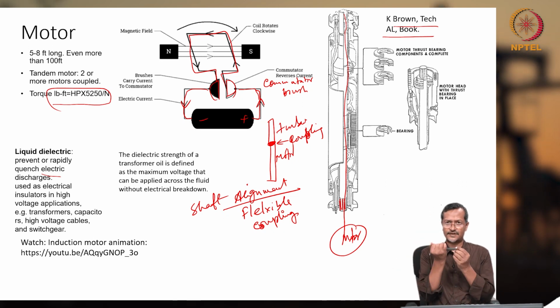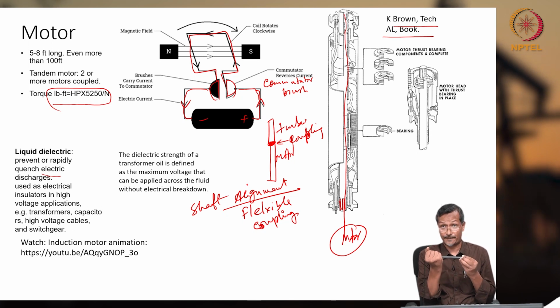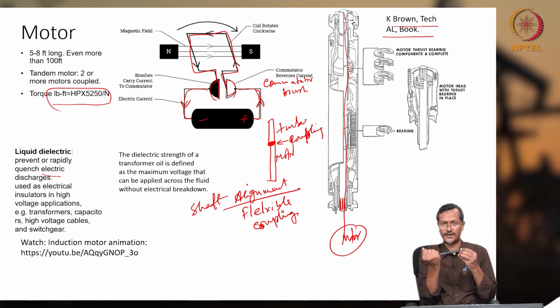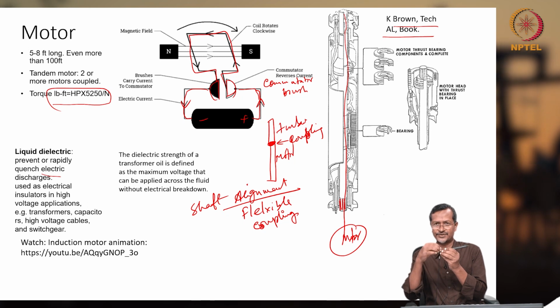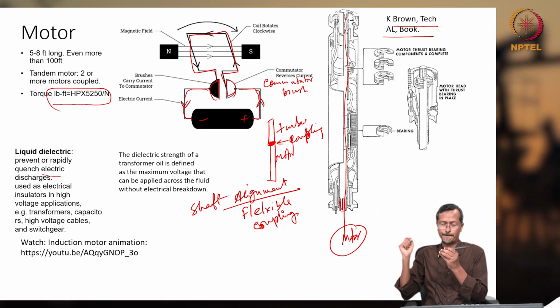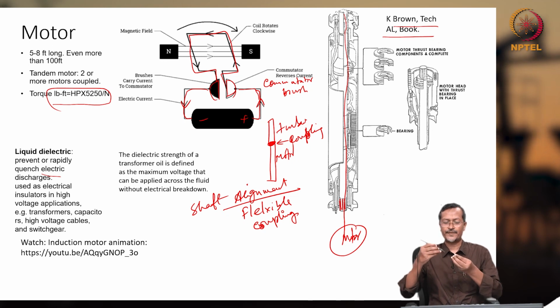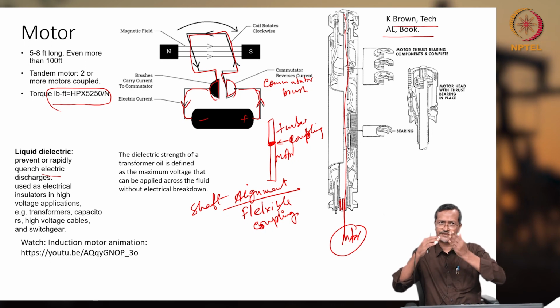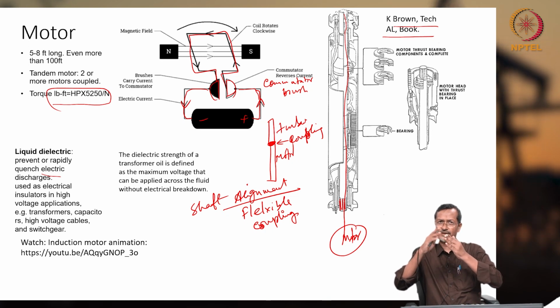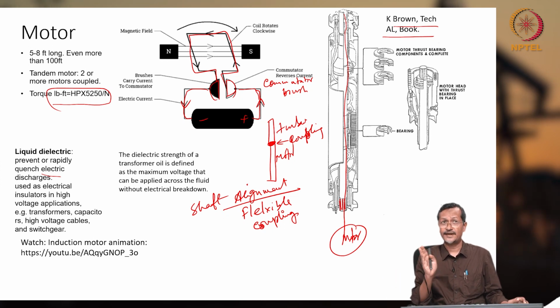So, you have to give some misalignment allowance through a flexible coupling system, so that one shaft should not transfer uneven forces to another shaft. Okay. And tandem motors are also created like that, so that one shaft is connected and a little bit of flexibility is given. So, with some misalignment, it will only be transferring torque. So, a shaft is entitled to transfer torque, not any other forces.